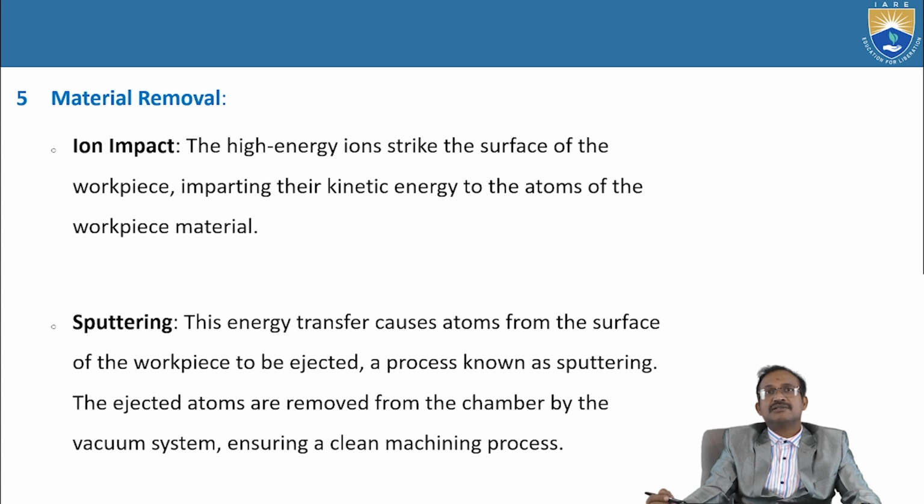The ions will strike the workpiece material to remove the material on the surface of the workpiece. So the ejected atoms are removed from the chamber by the vacuum system. So always we have to ensure the vacuum environment in the chamber.